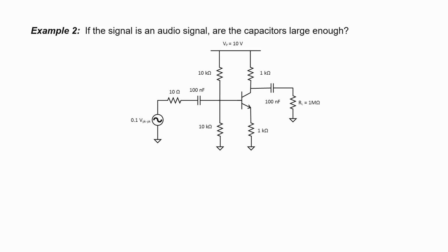Let's see what happens. Let's look at the resistance going into that amplifier and label it Rn. If you've seen my previous video on one-pole filters, you'll immediately recognize this as a one-pole high-pass filter. What's the corner frequency of that filter? That's what we're going to calculate right now. If we plug in R sub n, which is about 5 kiloohms, 10K in parallel with 10K, and a C of 100 nanofarads, then we'll calculate that the corner frequency here is about 318 hertz.